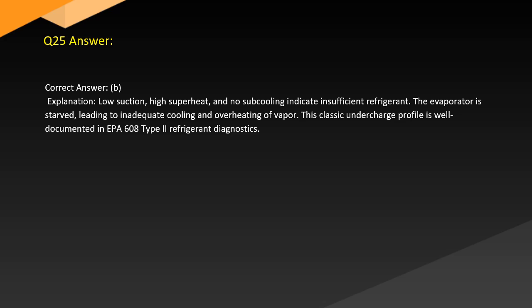Answer. Correct answer: B. Explanation: Low suction, high superheat, and no subcooling indicate insufficient refrigerant. The evaporator is starved, leading to inadequate cooling and overheating of vapor. This classic undercharge profile is well documented in EPA 608 refrigerant diagnostics.